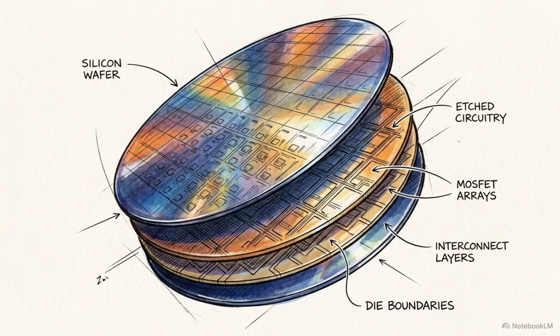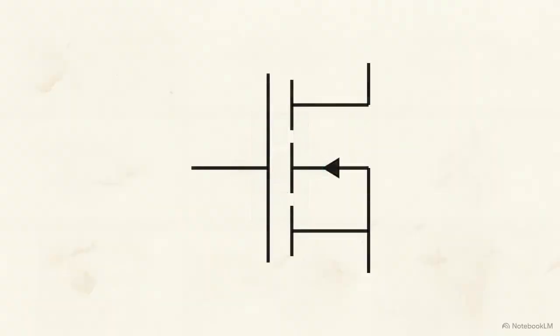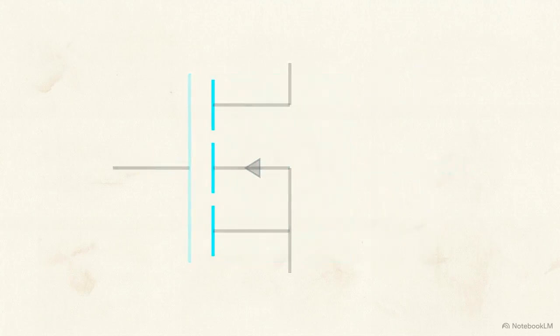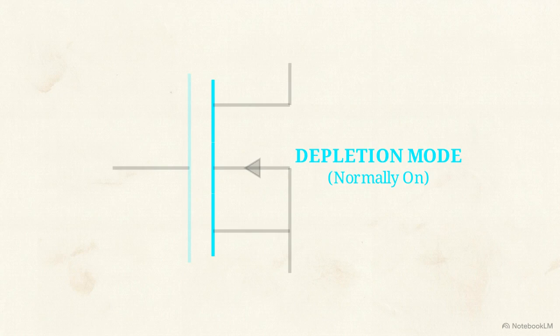We can see this codified syntax at work by analyzing a single complex component, the 4-terminal enhancement mode MOSFET. Even in North America, this symbol is governed by the strict rules of the IEEE 315/1975 standard rather than artistic preference. Constructed from a strict syntax of primitive elements, the vertical lines map to the physical silicon architecture: gate, gap, and channel. A broken channel line indicates an enhancement mode device, communicating the channel isn't continuous. A solid line represents a depletion mode transistor.